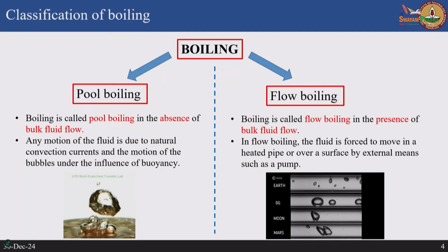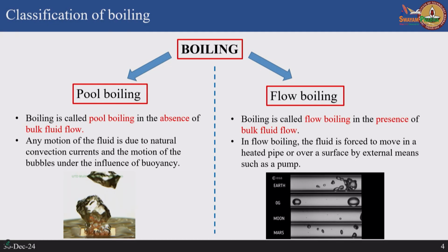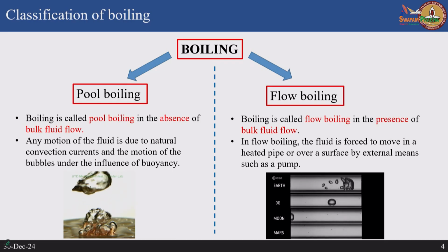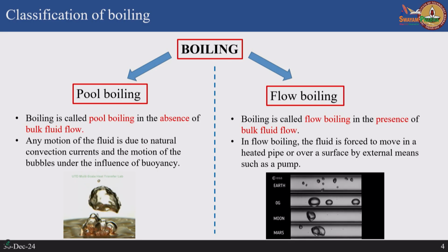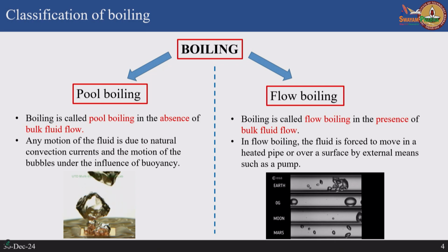And when we classify boiling, we talk about two kinds of boiling phenomena. One that I was just explaining, when you fill water in a container and you heat it, is called pool boiling, because there is no bulk flow. You do not pass the fluid in a tube or something, it is just a container, and boiling is taking place within this stationary pool of liquid. This is called pool boiling because there is an absence of bulk fluid flow.